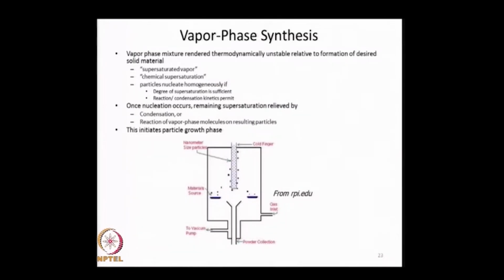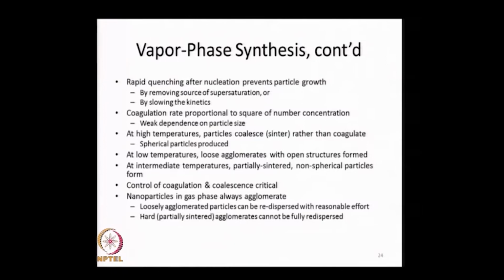If you recall that trimodal particle size distribution that we had sketched in one of the earlier lectures, the nucleation process has to be followed by a growth process in order for the cluster sizes to keep increasing. Now, sometimes you do not want the growth, you want the nuclei to remain as nuclei, you want the dimensions to remain essentially a few nanometers in size rather than growing to tens or hundreds of nanometers. Then what you need to do is quench the growth. So, do not allow the particle growth to happen.